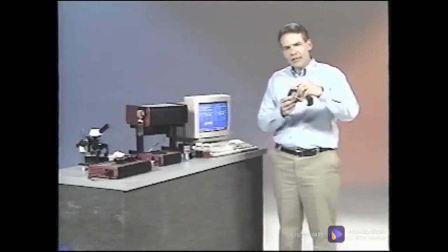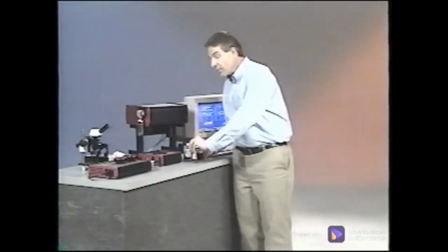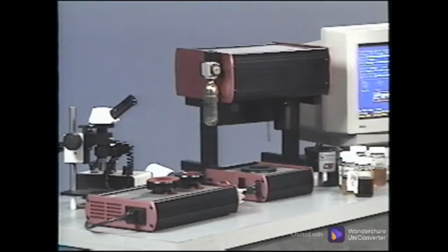With the most advanced tests being performed in an off-site lab. Machinery lubricants can be analyzed similarly, and for each machine, there may be only a few tests required. And like blood tests, an instrument produces specific results, so many instruments may be required for multiple tests. These devices here are tools commonly used for on-site oil analysis. Each of these is designed to provide particular information about the oil.